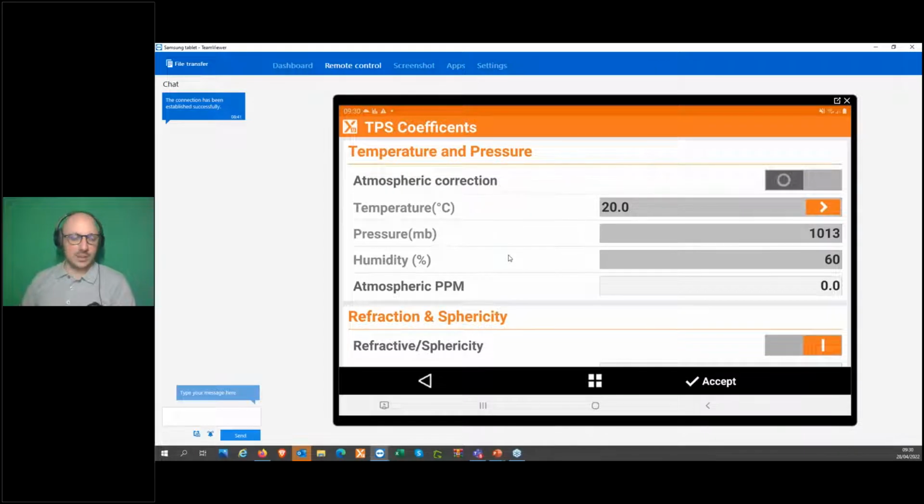So as you know, the distance measured with a total station is influenced by the temperature, the pressure, and the humidity. And you define what are called atmospheric PPM, then applied to the total station measurement. The problem is that if you activate them, you need to know, in the field, what is the temperature, what is the pressure, and the humidity. But of course, you need to search on the internet. You don't go on site with a meteo station.